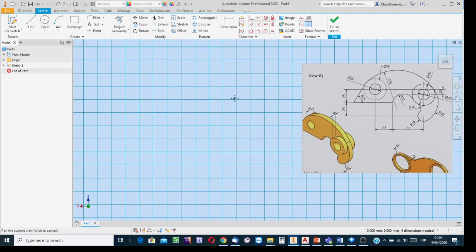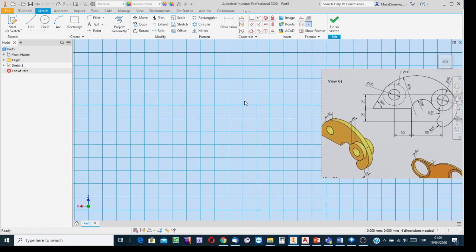But here this is the sketch environment, and in drawing the sketch we use in Inventor only one line type, the continuous thin line. Although I know that this hidden circle is the image of that hidden feature, so it is hidden.